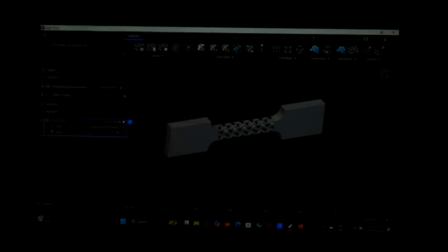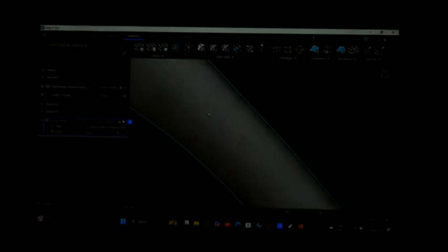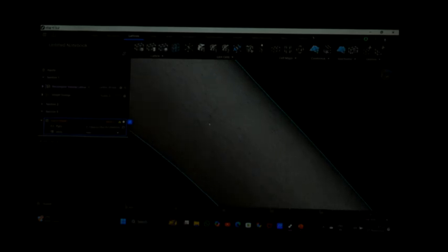See, this is a meshed file, you can see here. As I told you, STL is all about tessellation, triangles. You cannot find any square type of thing. This is all about triangles only. First we will convert this mesh body into an implicit body, then only we can play with anything. So convert here, type implicit. We can see here, this is an implicit body from mesh. From mesh only we are getting implicit. So I will take that.